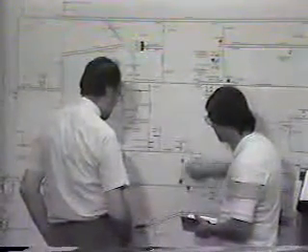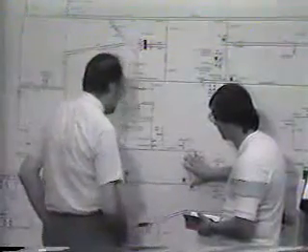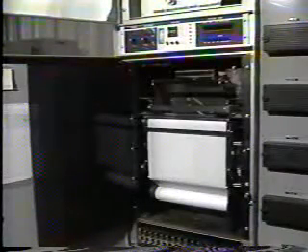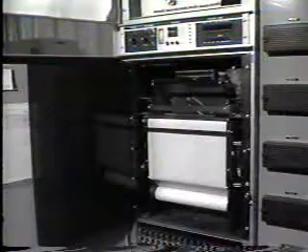With all of the variables involved, it's often quite difficult to carry out this post-mortem and deduce what actually happened. Fortunately for us, nowadays most power systems have installed data recording equipment, oscillographs and fault indicators that will indicate conditions before and after the fault. These provide valuable assistance in evaluating the actual performance of the protection system.